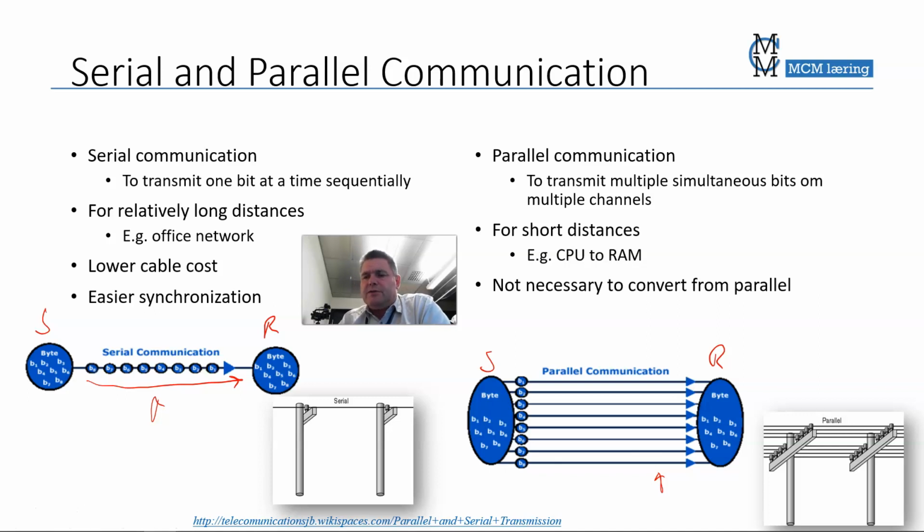when the data communication rate goes up, when the speed goes up, you have really big problems with synchronization, because the bits here that are sent simultaneously will not be received simultaneously, so they will maybe spread like this. And you have serious timing issues or synchronization issues with faster communication. So therefore, for most systems, serial communication is actually faster.